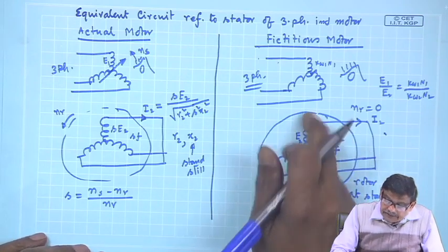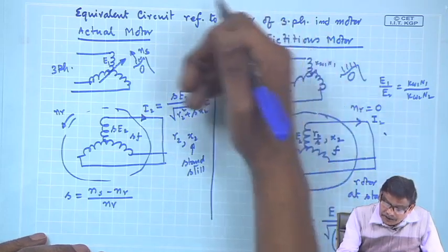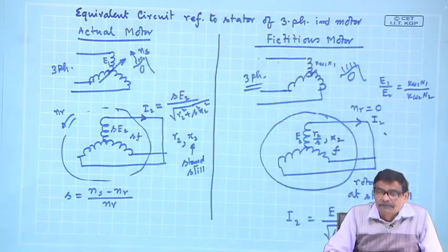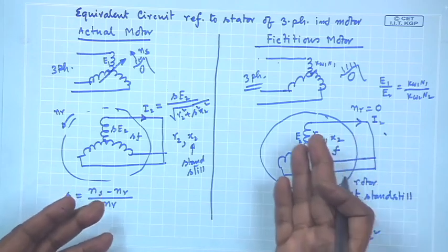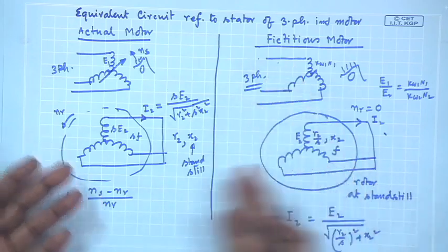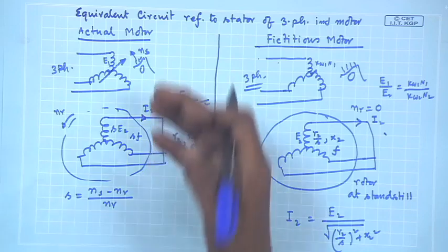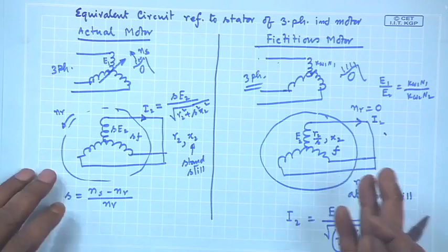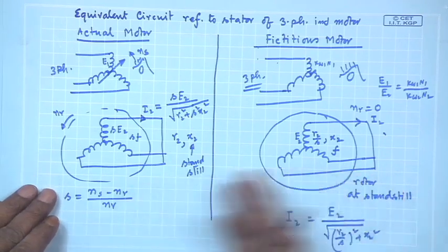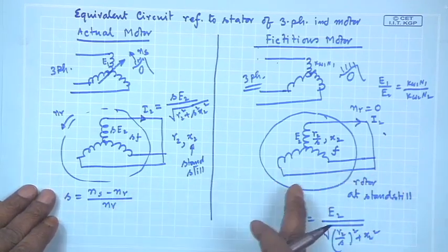In this case, the same total power it will draw, because the stator will react in the same way in both the cases. So, whatever extra current it draws is decided by the rotor current and its power factor angle, those things are remaining the same, magnitude of the rotor currents and so on.